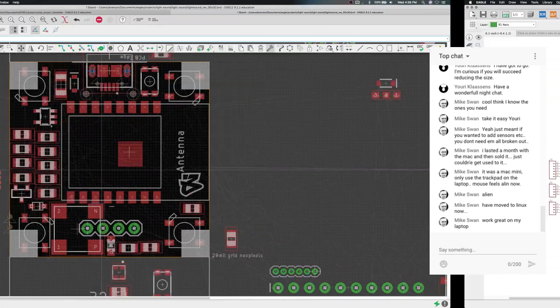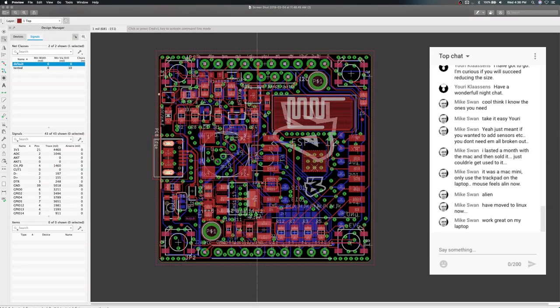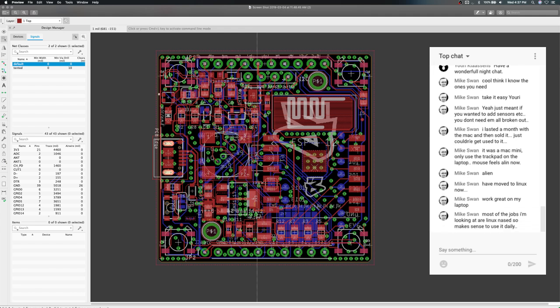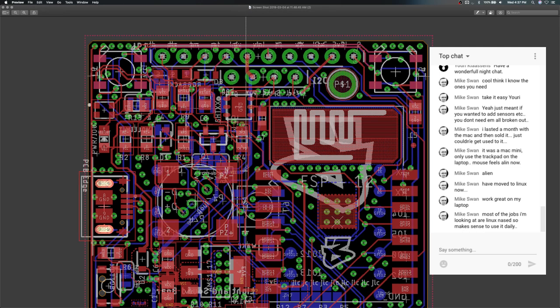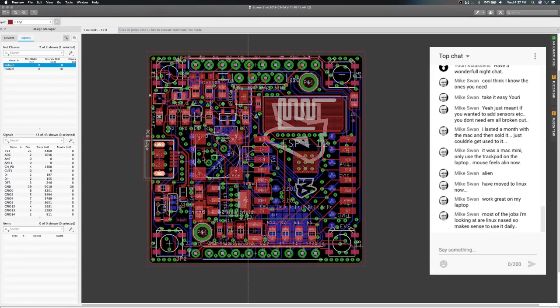Yeah, like on my other board, my idea was to put an I squared C header here. But then I started looking, and you're never going to hit all the I squared C headers unless you put VCC, ground, data, VCC, ground, ground, VCC. You'd have to have every combination, the way the SDA, SCL. Sometimes it's the power that's reversed. Sometimes it's the SCL. These you can fix in software, the data lines, but you can't fix the power and the ground unless you had some kind of toggle there. But it'd be cool.